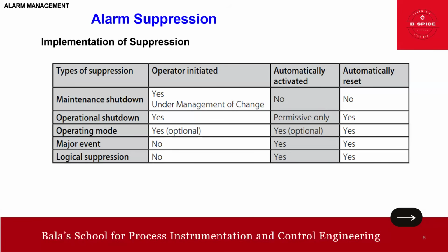And one point I want to tell you, friends, during the design we should do the suppression configuration. For an existing system, it should only be added within the framework of the MOC. The potential effect of the proposed schemes should be assessed to ensure that there are no scenarios where suppression would hide a situation from the operator that may require a response. However, the assessment should not be overly pessimistic. That is also what we need to focus on, because failing to suppress can result in regular irritation, which creates its own issue.